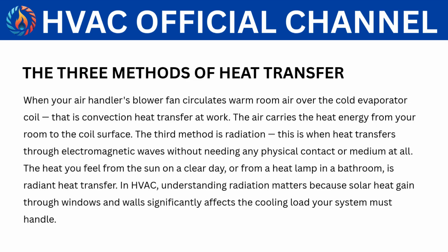The third method is radiation. This is when heat transfers through electromagnetic waves without needing any physical contact or medium at all. The heat you feel from the sun on a clear day or from a heat lamp in a bathroom is radiant heat transfer. In HVAC, understanding radiation matters because solar heat gain through windows and walls significantly affects the cooling load your system must handle.